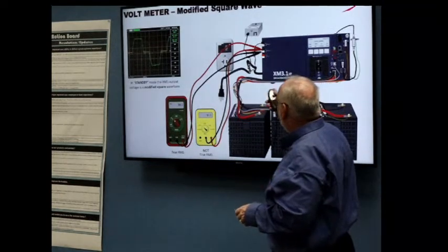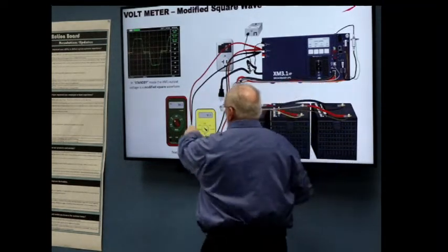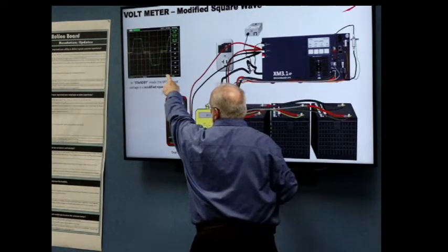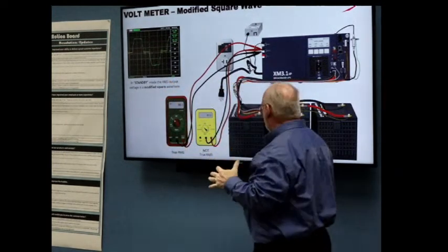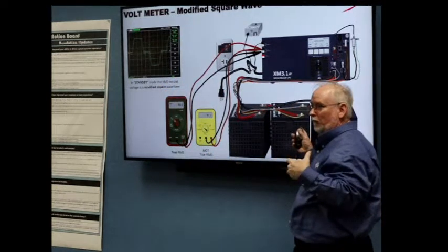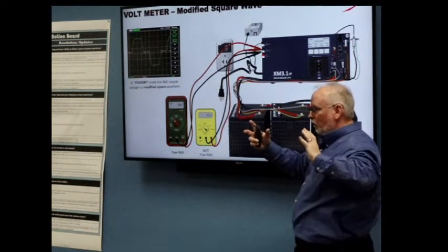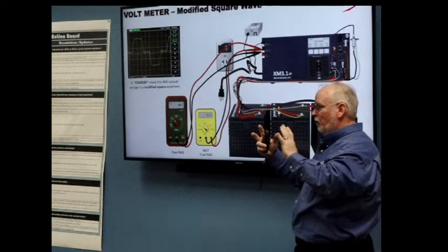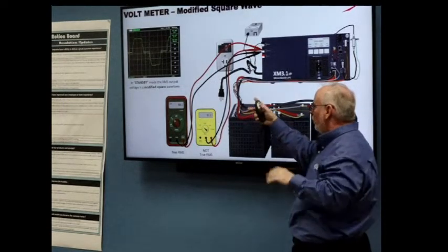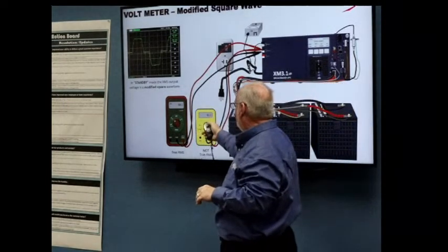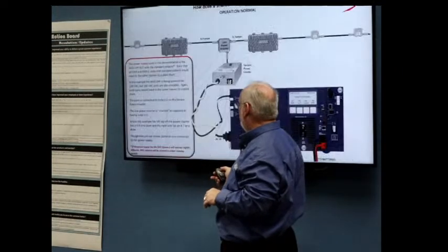And then when you look at the power supply in standby, same thing. We're outputting almost the identical voltage. We've changed the duty cycle. This is how we extend the battery life during discharge. So we don't always hit it with all the energy. We actually reduce the energy to produce the amount we need to power the plant. But again, a non-RMS meter won't measure correctly.